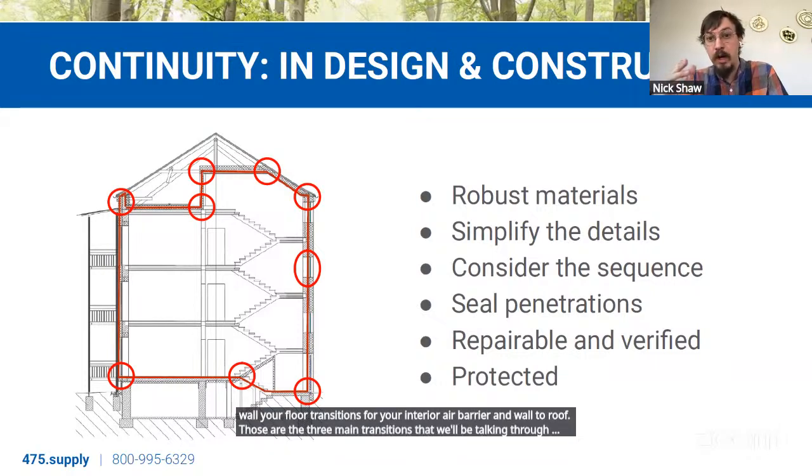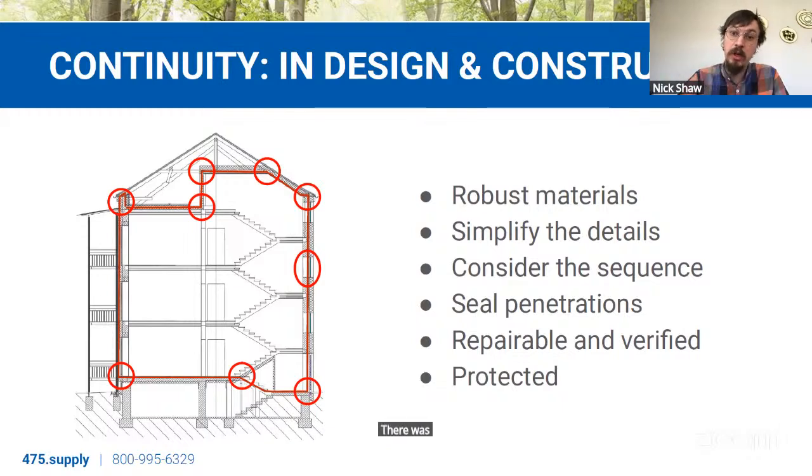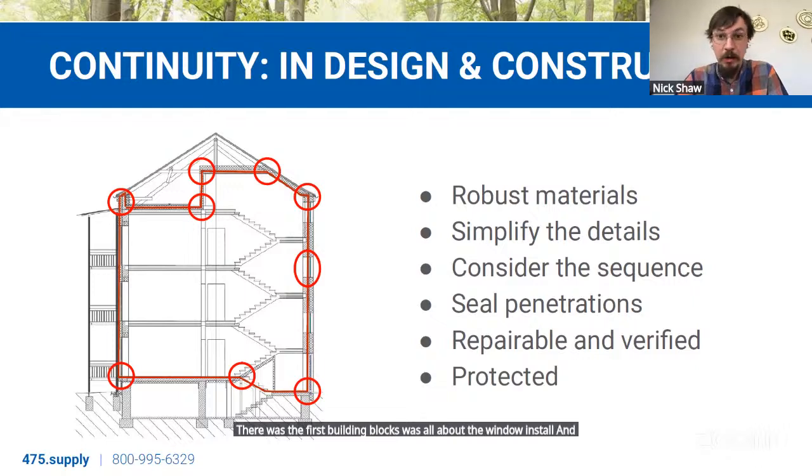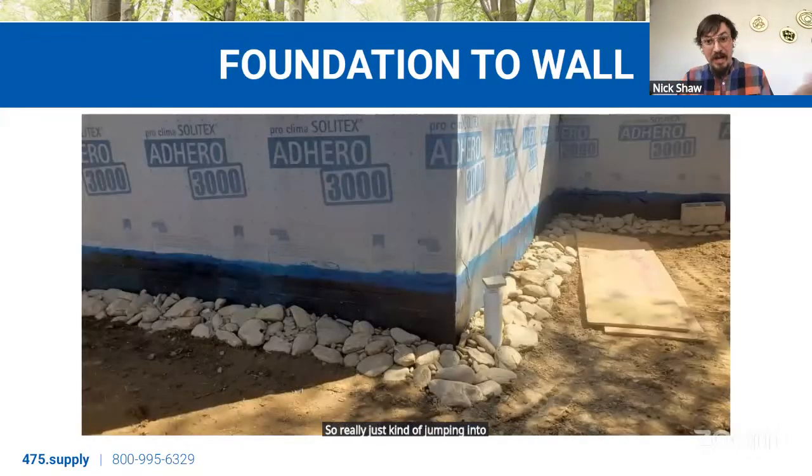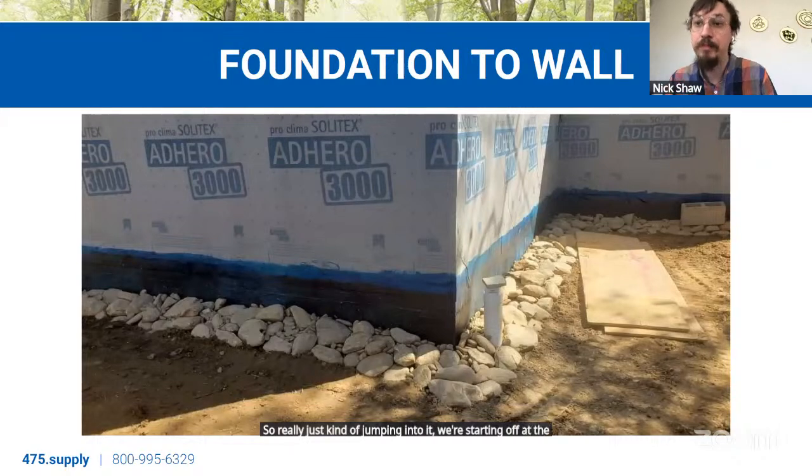The first building blocks was all about the window install. And that is, of course, a major air barrier transition. Your window is your airtight layer in that plane. So really just jumping into it, we're starting off at the base, at the foundation to wall.